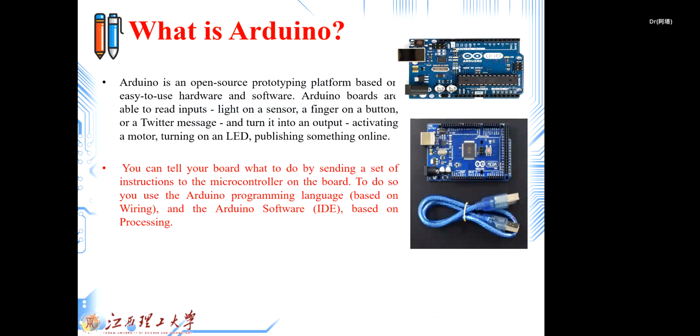When you wanted to program any microcontroller, you should remove the chip, put it in a tool that we call a programmer, connect it with the serial port to the computer, load the code on the IC, and then remove the IC, attach it again on the main board, and see the performance.